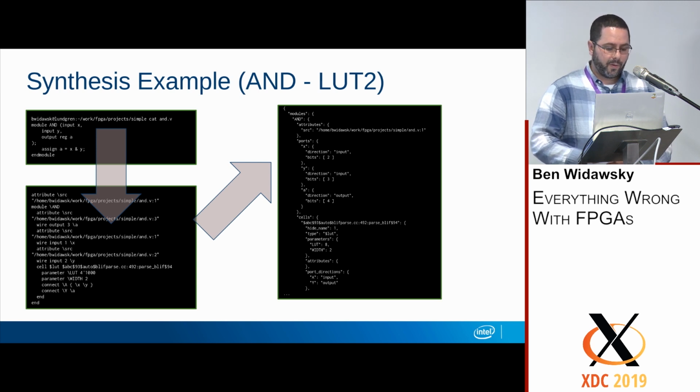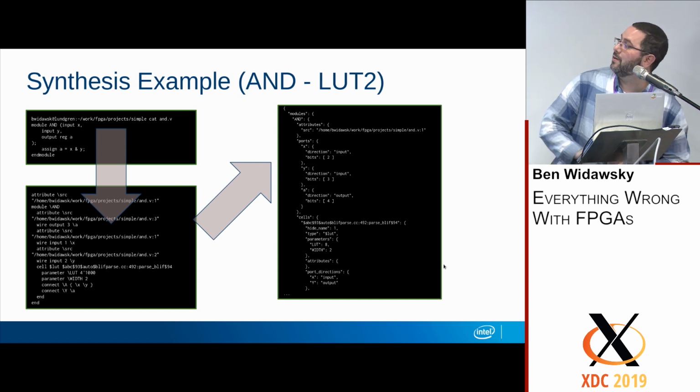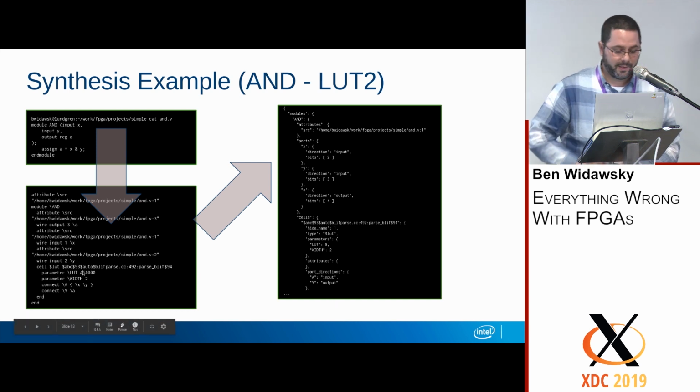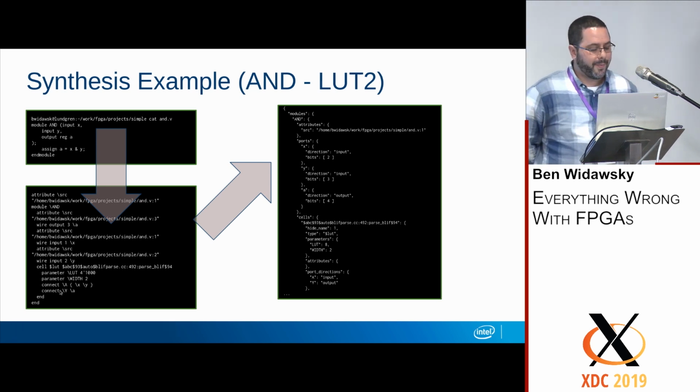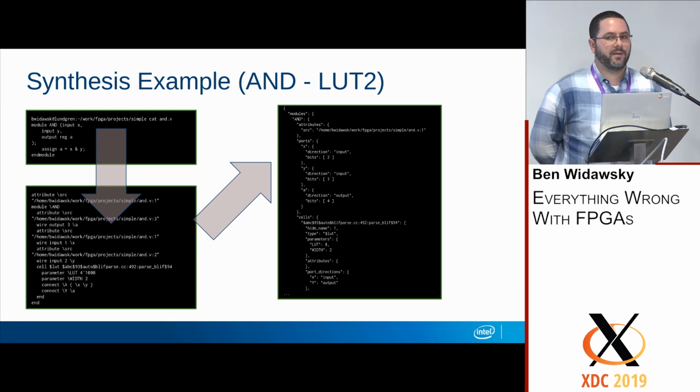In the bottom left corner, you have Yosys's RTLIL. It's their intermediate language, and it's exactly what it sounds like. It's an intermediate language that, in this case, is quite simple. It's telling us that there's a LUT, and it has a width of 2. I can't really find my mouse over there, but you can take my word for it. There's a generic synthesis script in Yosys that allows you to say, hey, I have a 2-LUT FPGA or underlying device, and please synthesize for that.